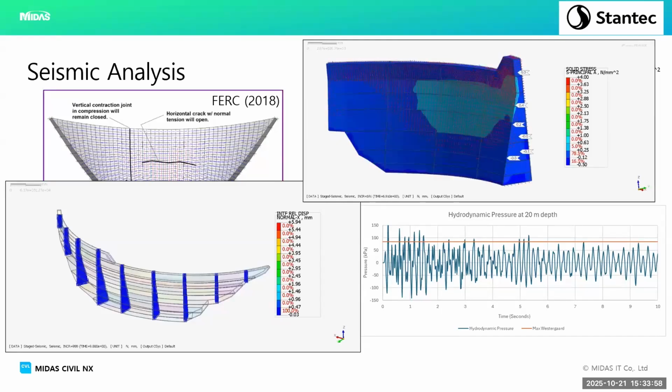And at the base, on the heel, you also get high vertical tensions, and that will be debonding. At the interface of the heel, when you get uplift and it peels away and you get increased uplift load and it peels away, essentially what that does is it throws more arch stress into the abutments and less shear demand on the center monolith. Less so with the wide U valley, but it does nonetheless. So that's just a couple of nice videos.